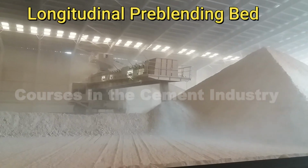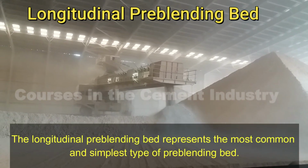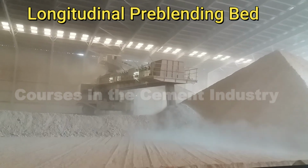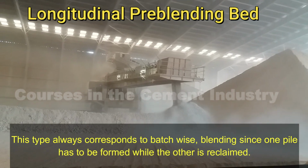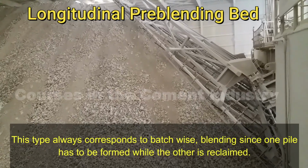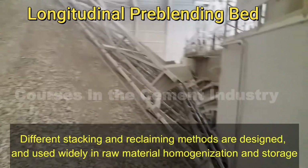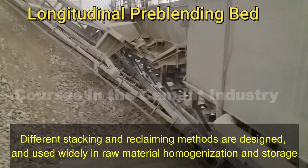Longitudinal pre-blending bed. The longitudinal pre-blending bed represents the most common and simplest type of pre-blending bed. This type always corresponds to batch-wise blending, since one pile has to be formed while the other is reclaimed. Different stacking and reclaiming methods are designed and used widely in raw material homogenization and storage.